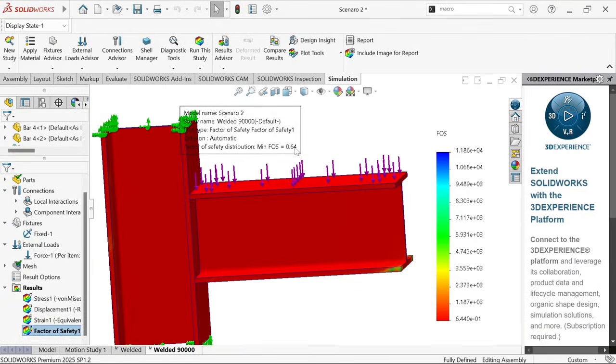Factors that actually play into it. You don't want to go, let's say your brake is built with a factor of safety of exactly 1, right? And the force you can apply on it is 500. And then one day you're moving and you almost hit the cut, and you want to try your best and just dodge, and then you mistakenly panic and exert a force above 500, and then it just breaks. That's going to be catastrophic.